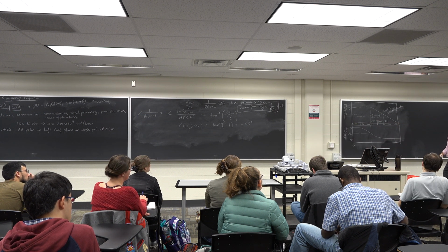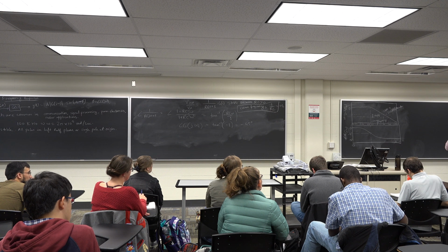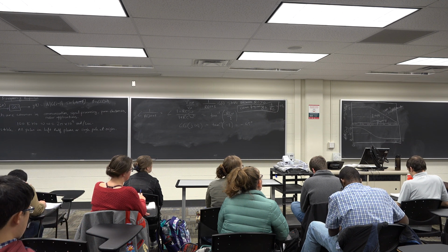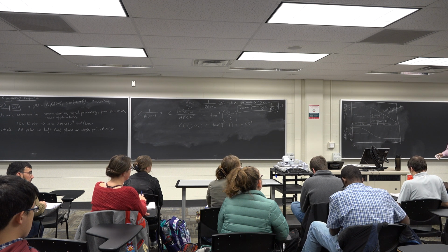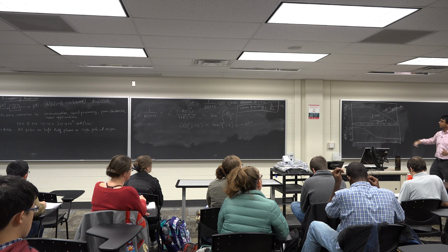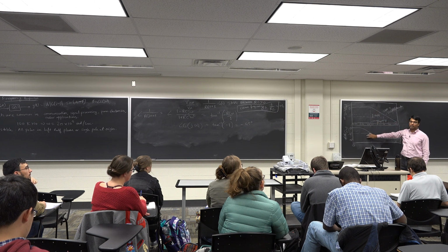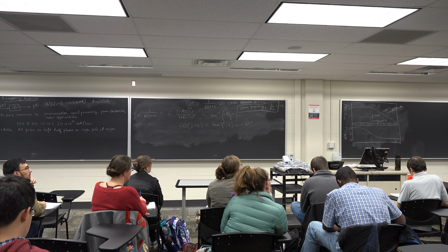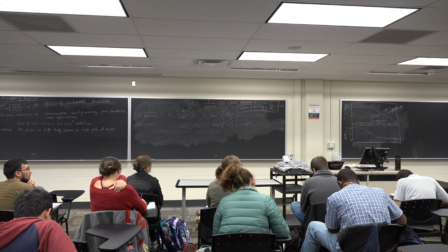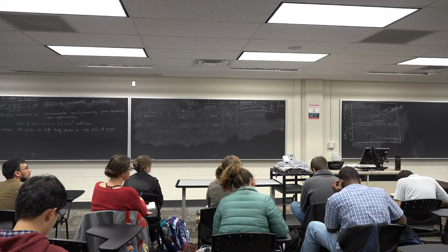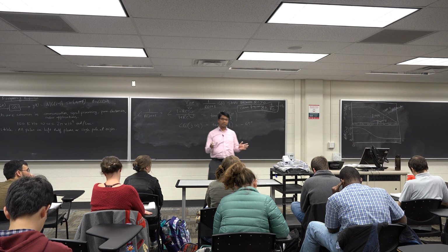So these are all the things you can infer from looking at the Bode plot, and that's the reason why the Bode plot was so useful. I have a very complicated system with vacuum tubes and whatnot, and I just don't have an understanding of how to model these systems. So I'm not going to even think about modeling them. I'm going to put in a sinusoidal wave and look at the output. I am going to plot the magnitude plot and the angle plot, the phase plot, and based on these two pieces of information, I am going to infer what the approximate transfer function for that system looks like. And using that transfer function, I can design amplifiers or rectifiers or demodulators and things like that by picking an appropriate control system for that circuit.